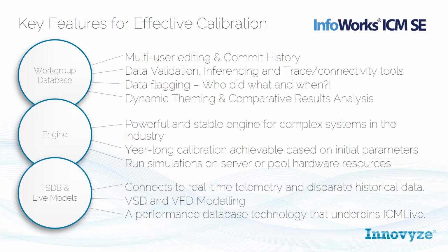And then on the consulting end of things, or on the utility or council end of things, you have multiple sources contributing to the model itself. Do you find yourself using the data flagging so you can understand whether it was GIS or a design drawing, the source of information? Yep, the data flagging is probably critical to use. I would hope that anyone with a hydraulic model has made heavy use of it. Particularly when you're going through calibration, understanding the hierarchy of data is really important.